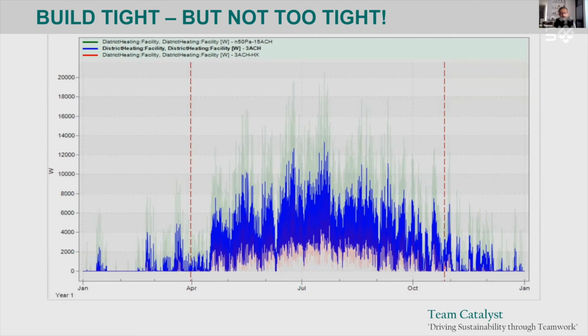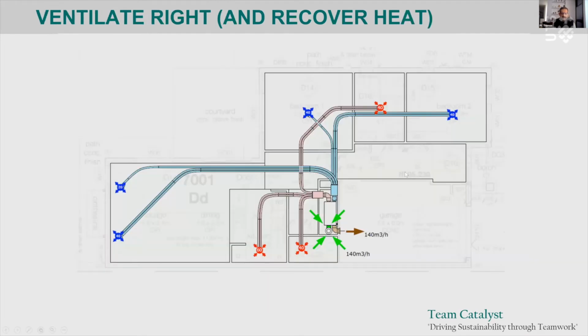So from Europe and the US, we've had what are called heat recovery ventilators. Okay, so what you've got is a little heat exchange box. You supply fresh outside air to the bedrooms and the living rooms. You extract polluted air with moisture from the bathrooms, the toilets, the kitchens, and then the magic box exchanges the heat.